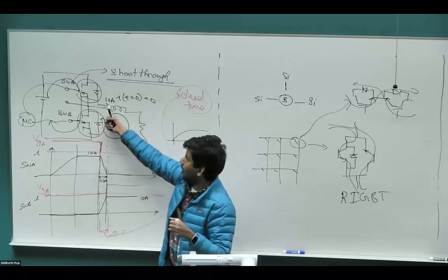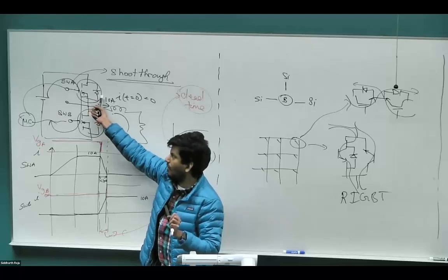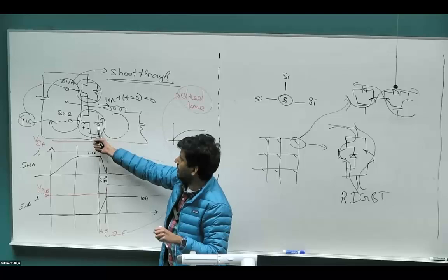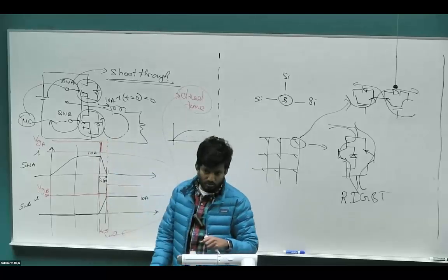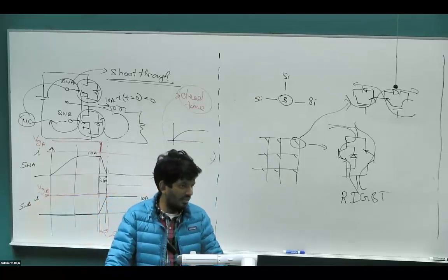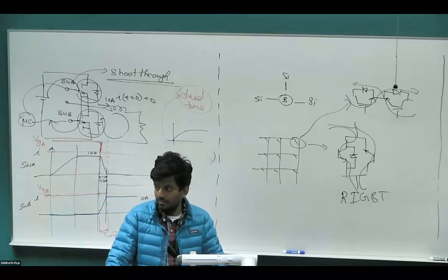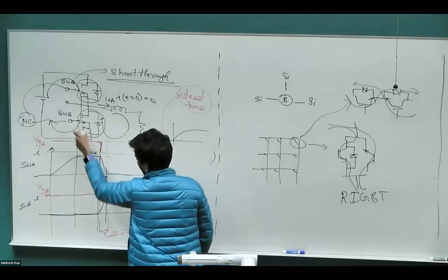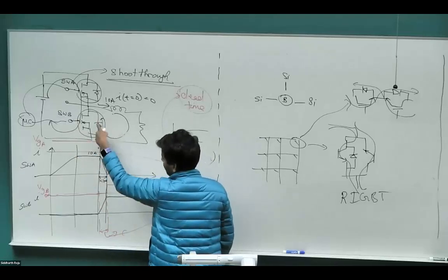Still, the top diode is yet useless for us as of now, but it will become useful a little bit later. But for now, only the bottom diode is useful. But why do we want to turn on the bottom switch? The bottom diode is anyway conducting. Why do we want to go to the switch? Lower losses. So we could have left the switch completely turned off and continued conducting through the body diode. That would be fine.